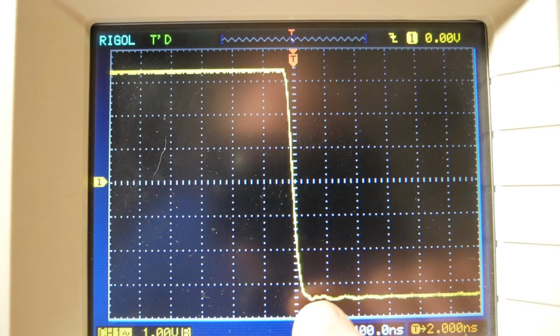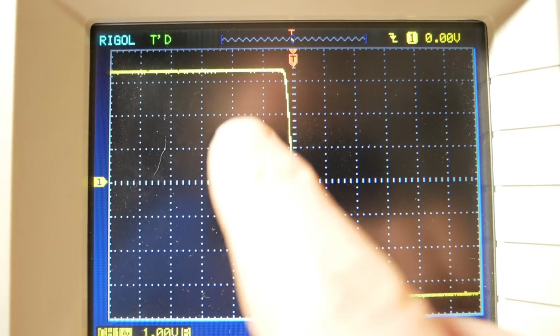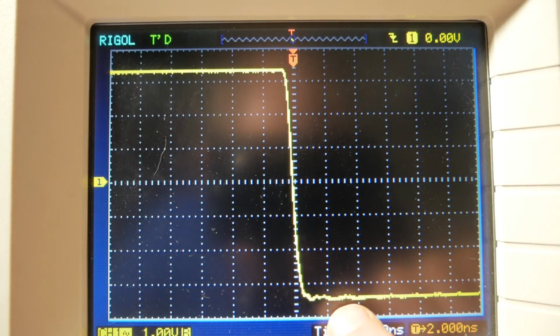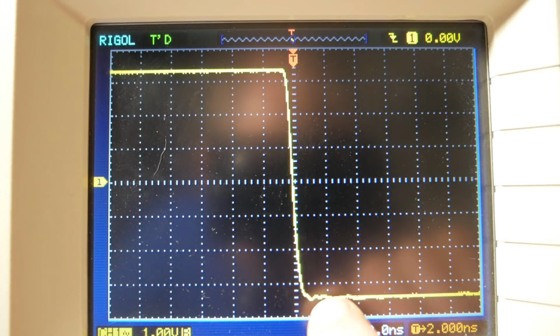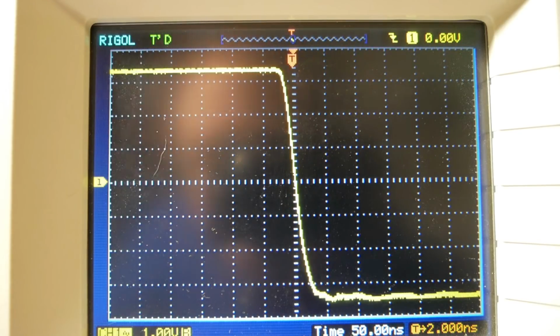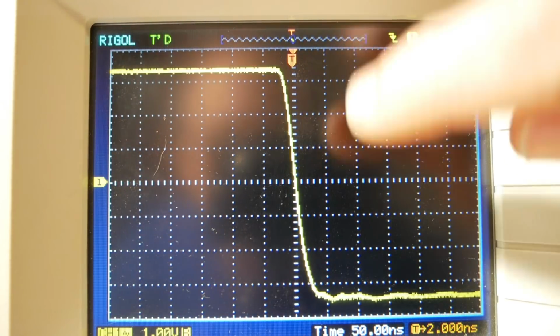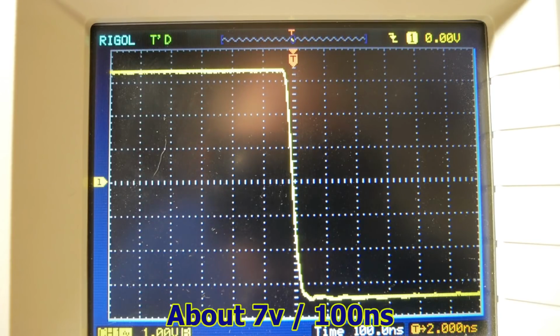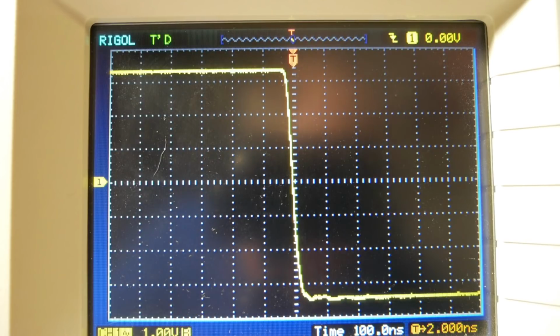Okay, so now I'm back on the LED CCS on the falling part of the square wave. This junk is mainly from the function generator. It's not oscillating like the other one did. And at 50 you can see the slew rate's about the same. So yeah, I'm kind of getting scared off that dual transistor circuit.